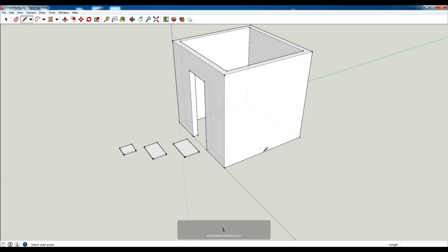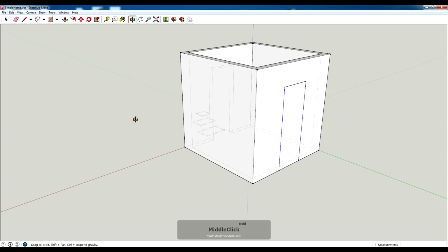And just for good measure, I'm actually going to make another door over here. I can make it the same way that I did last time, but a quick way to do this is because I have a square box. I'm using Control, holding that down. You can see there's a little plus sign next to my arrow key. So I'm just selecting these edges. I'm going to hit that Move command and choose this edge here. Control. And you can see that I copied this here.